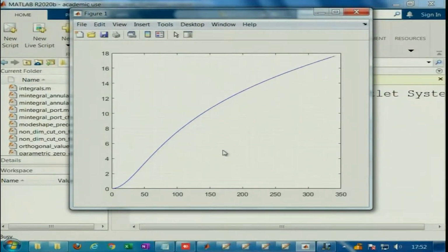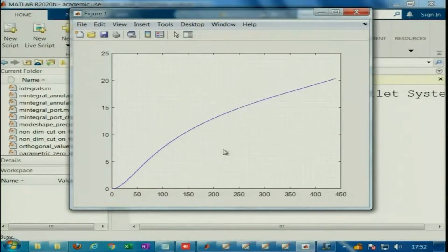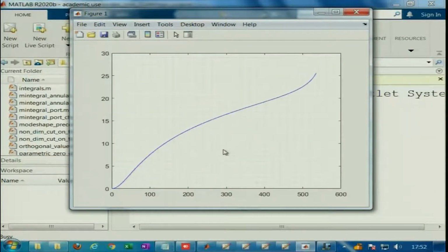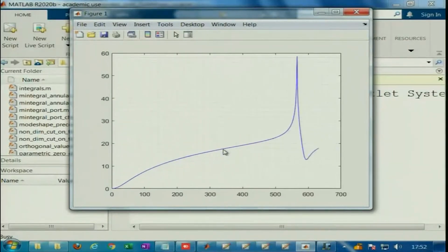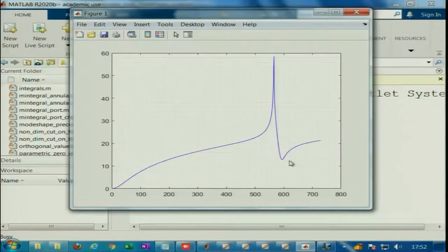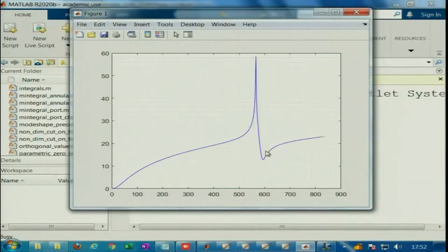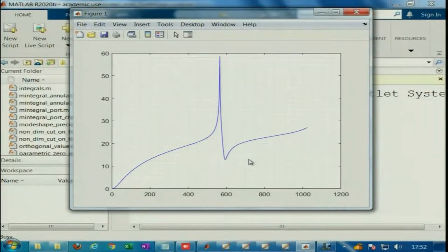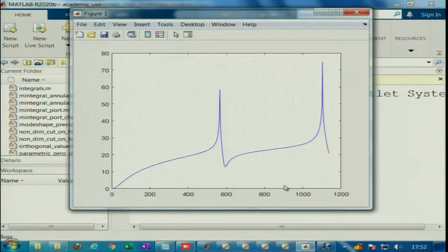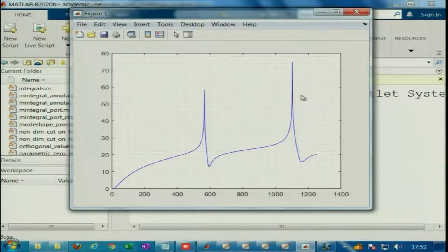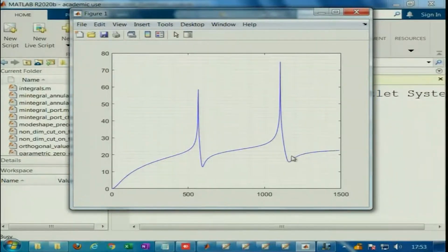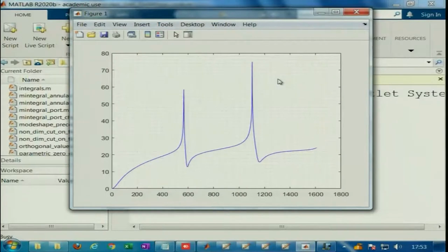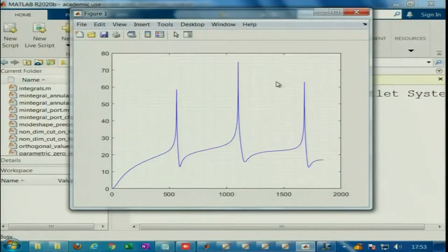So, all these things are okay, but what we really want to see is that the transmission loss has dropped down to about 12.5 dB, okay, and you get a peak here. The peak is not able to annihilate the trough. You can clearly appreciate the mistuning, and it is even more pronounced at the second axial resonance. So, this peak and the trough are not quite tuned, although you would see just with a small tuning you could do better. So, I will show you ways how to tune it incorporating the wall thickness effect as well.